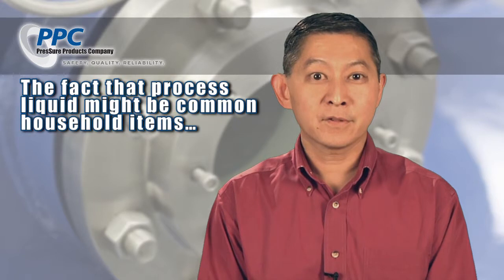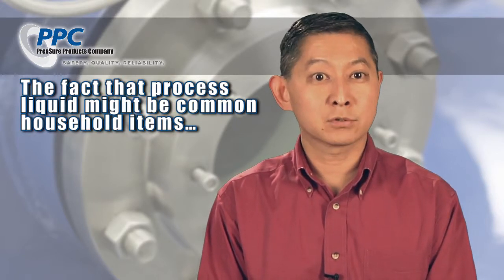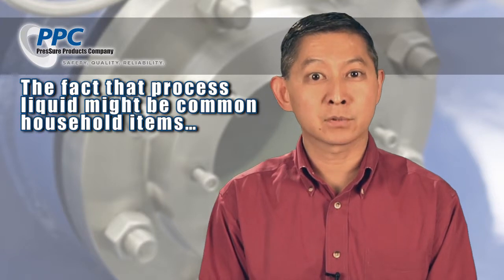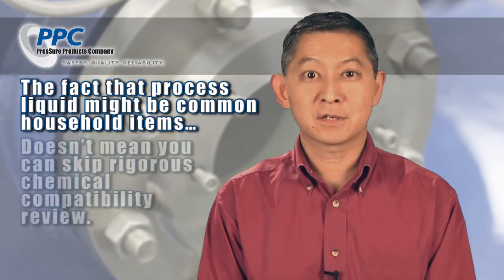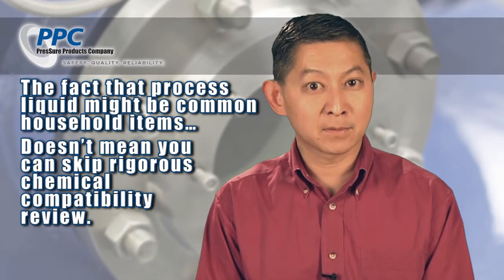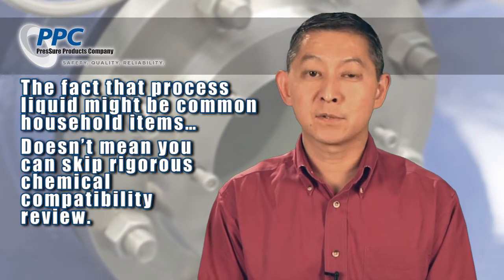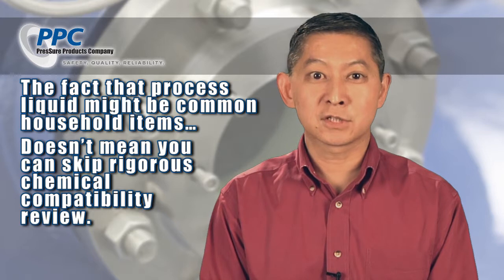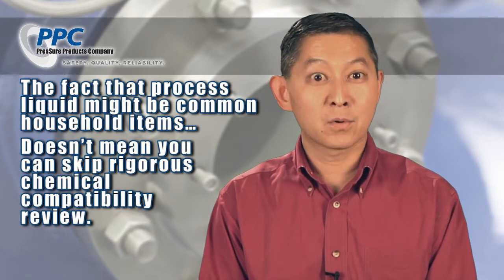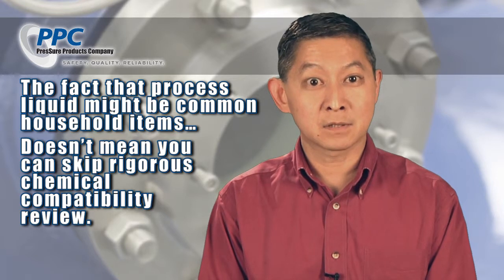In this video, I've intentionally talked about water. You don't need some exotic, toxic process to experience failures. Everything I described about water applies to bases as well, like potassium hydroxide, which you use as a household drain declogger. Fortunately, these failures tend to be slowly developing leaks rather than dramatic explosions. If your process fluid is just water, then the leak is just a maintenance hassle. If your process is some toxic liquid, that's a whole different story, even if the leak is slow.